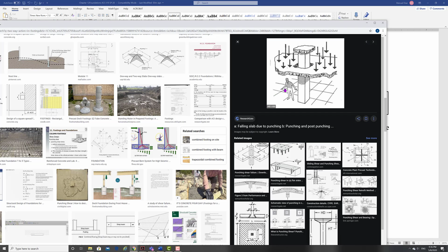Of course, there is the soil, and so it's less of a hazard, right? Because this one is going into air, so that's why the slab fails, because in slabs there is nothing else. But in the case of the footing, it is punching through, but going into the soil, so it's not that bad, but still, there is a punching shear effect.